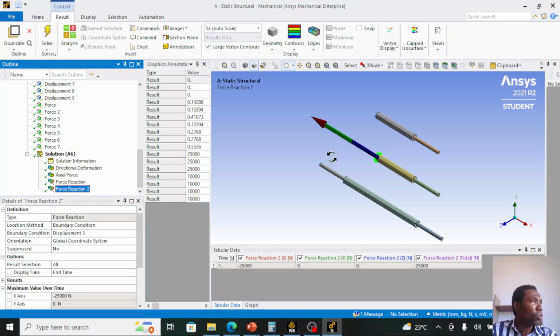I would like to show you one more functionality of the Ansys program before I end this video tutorial. We can actually mirror the color plot result of our half model. We can mirror the results so that we can visualize full results in the Ansys program. I will show you how to do this. So let me close this table here.